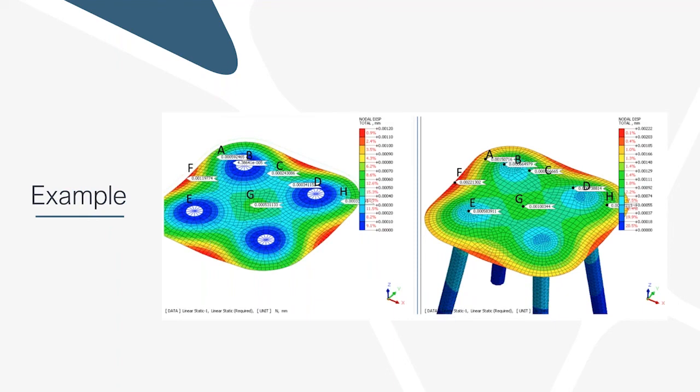So this is kind of a random example I pulled. I was doing a little bit of research on this, and I liked this example because it illustrates a red flag, I would say, that can often help you get to the right answer. This is an example of a model that's the exact same model, but has different boundary conditions. And the loads on the left-hand side are very concentrated in comparison with the loads on the right. And it's all due to the way the boundary conditions were established. This example had up to 1,500% difference between the results using the same model. So a red flag, I would say, anytime you see massive force concentrations, definitely something to look at. Is that actually real? Because again, the relative stiffness issue comes into play.